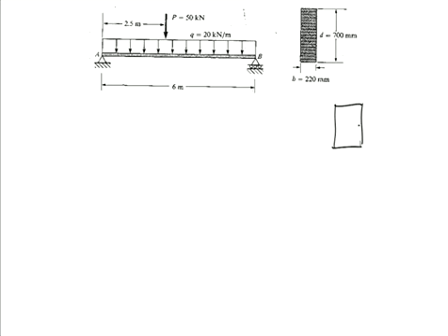But when you have a rectangular beam of width B and of depth D, when you consider bending about the horizontal axis, the I value here is BD cubed on 12. So that's something you need to memorise, something you need to be familiar with. Now I've said here bending about the XX axis.